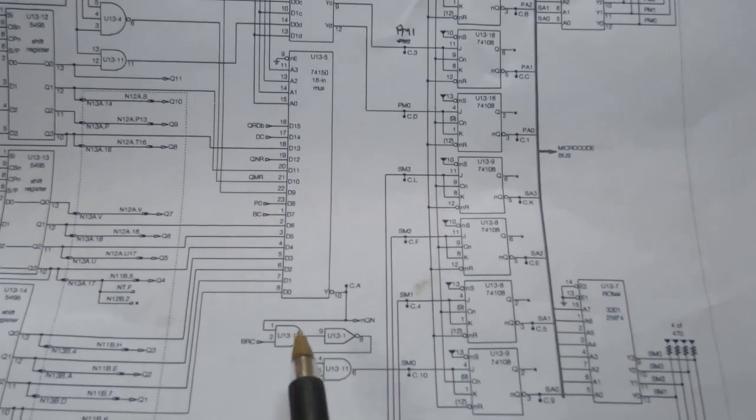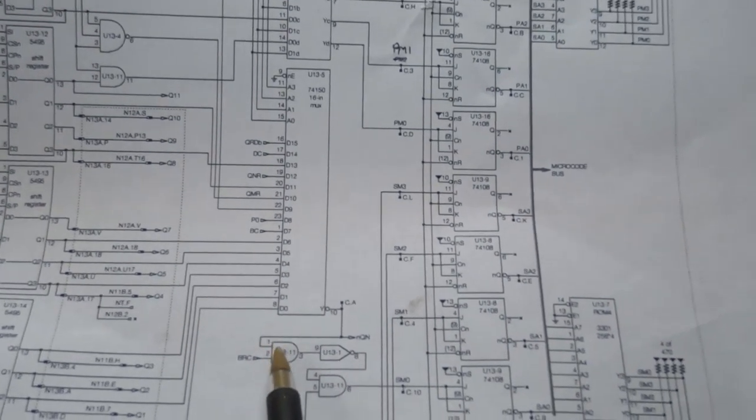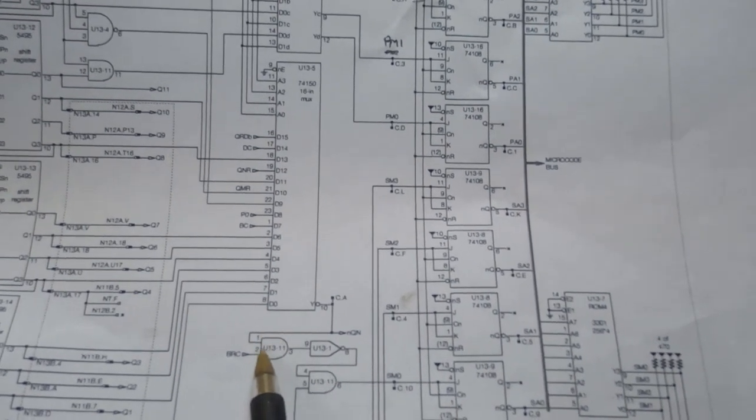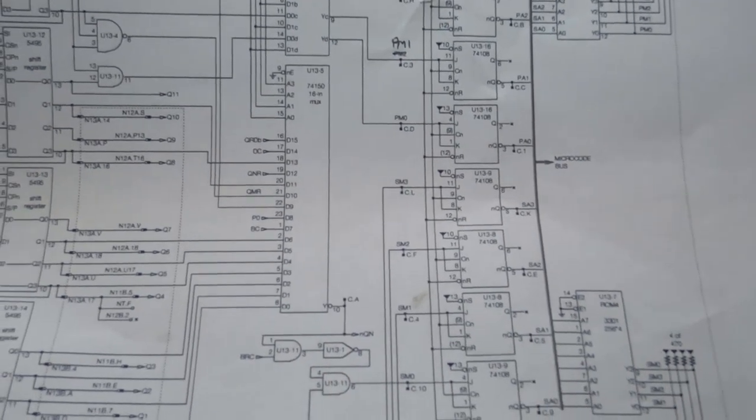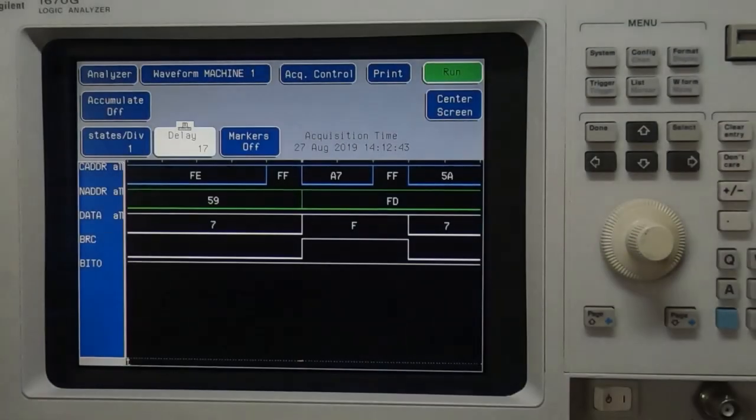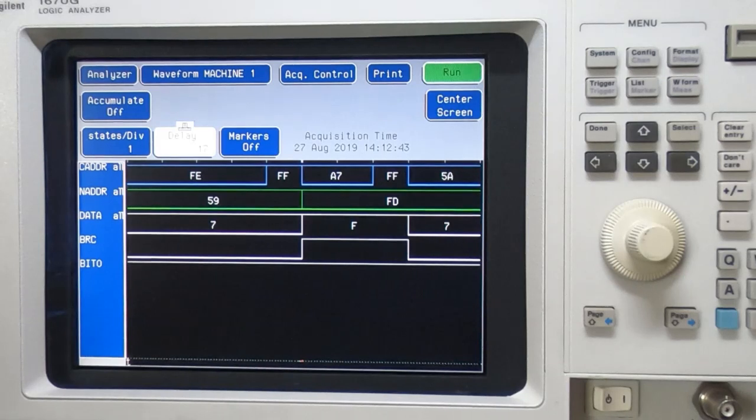so there's something wrong in this circuit somewhere. So what I'll do is I'll get the scope and we'll look at these points. So we'll look at this first gate and the second gate and see what these are actually doing. I'll reposition the camera, I'll turn the analyzer off because it's a bit noisy, and we'll see what's going on with those logic gates.